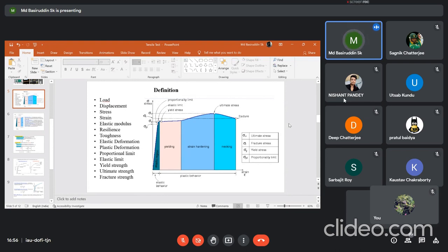We can take the change in cross-sectional area. Can we take that one? If we take that one, then how can we correlate? Because the volume remains the same, we can replace the gauge length in terms of cross-sectional area, right? Because this is only the localized deformation region. So we can consider the initial gauge cross-section as well as the instantaneous cross-section of the gauge, right?